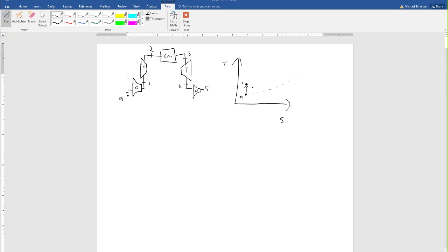This is at some other pressure. Then here, this would be the ideal compressor, 2S, up to some high pressure over here. But the real compressor is going to go over here to state 2. Then we're going to add heat up here to state 3. Then if we had some ideal turbine, we'd go here to 4S. But a real turbine is going to go down here to state 4. And then we'll still assume that the nozzle is isentropic down to state 5.